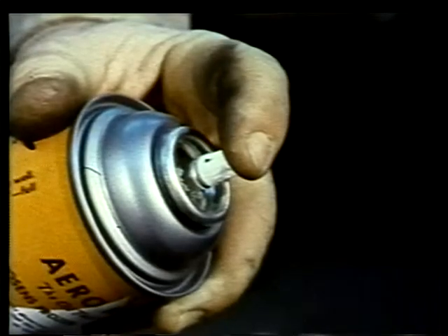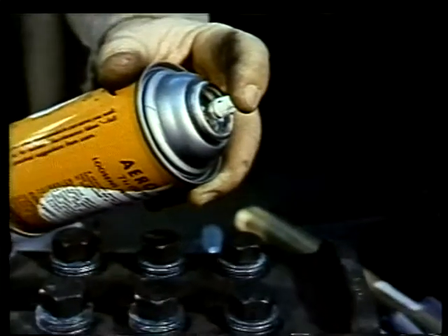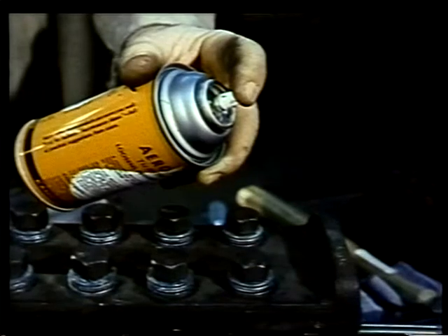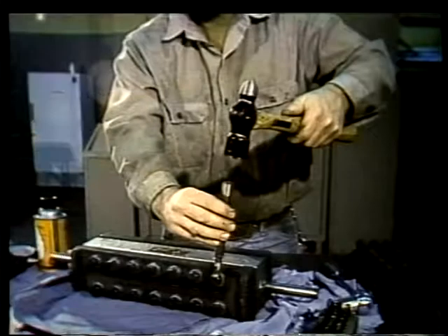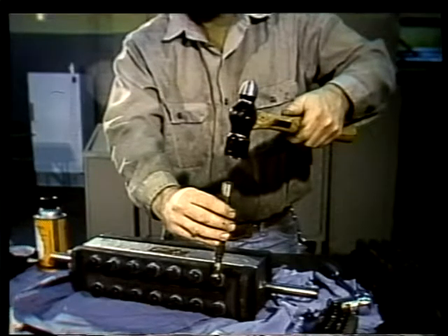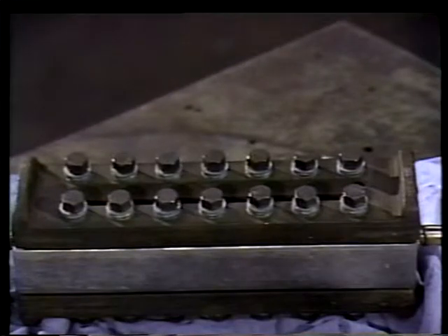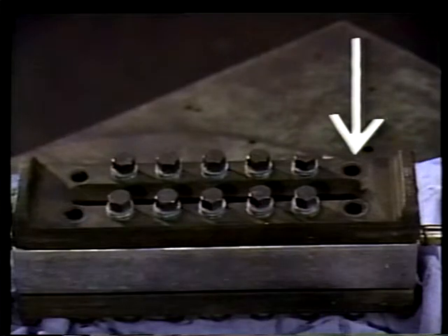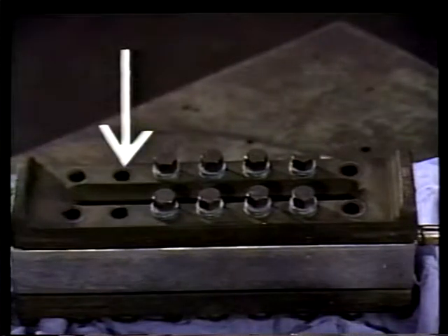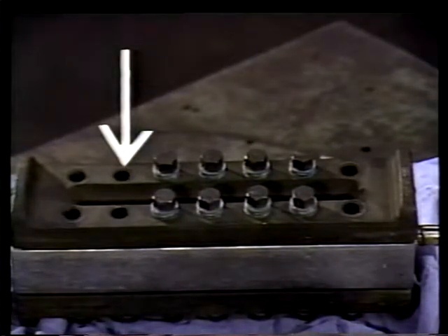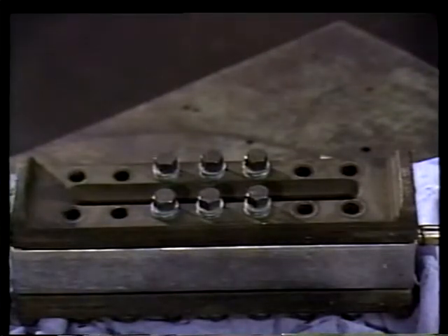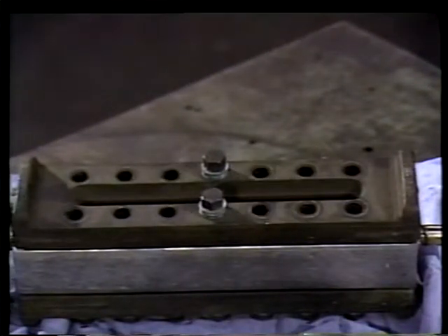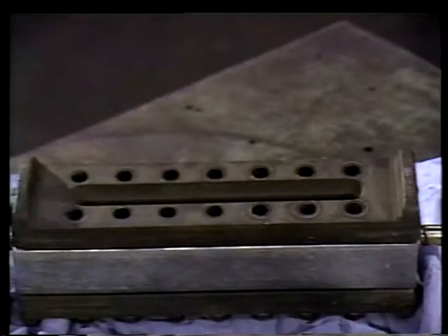If the bolts won't loosen, try soaking them in penetrating oil. If they're still tight, take a hammer and a brass rod and rap the flats of the bolt heads. That should loosen them. Remove the two bolts at one end of the gauge, then the two at the other end. Remove the next pair of bolts from the first end, and then the next set at the other. Alternate from one end to the other until all the bolts and washers are removed.